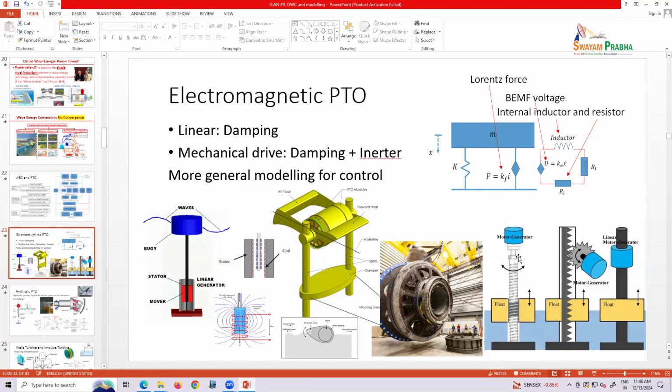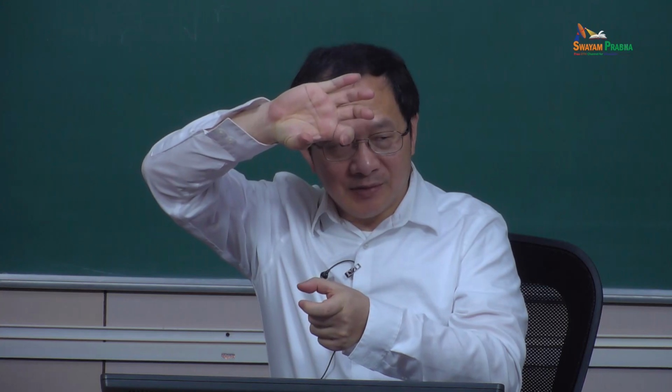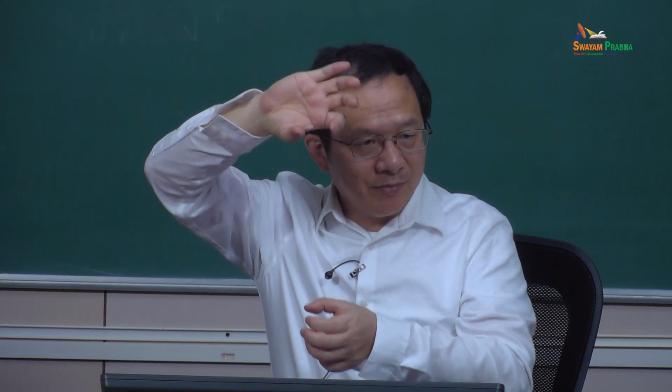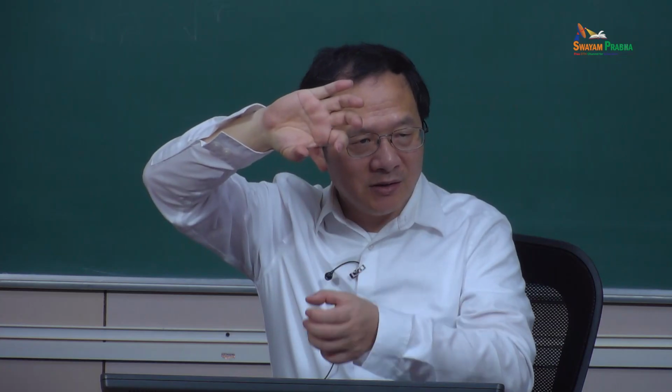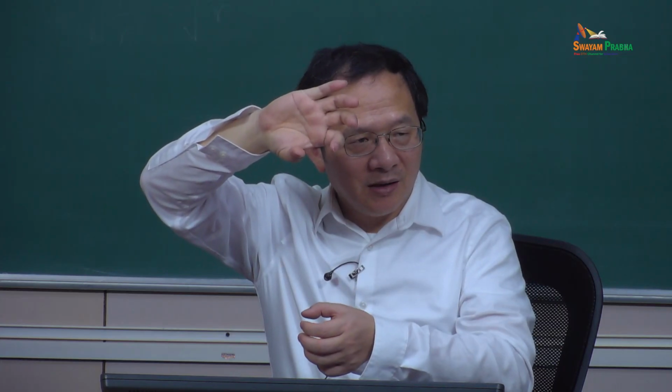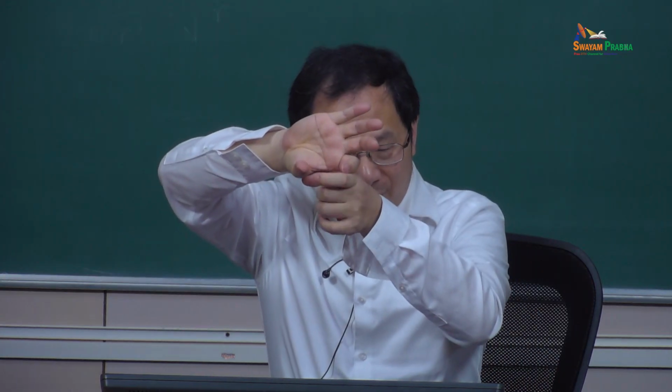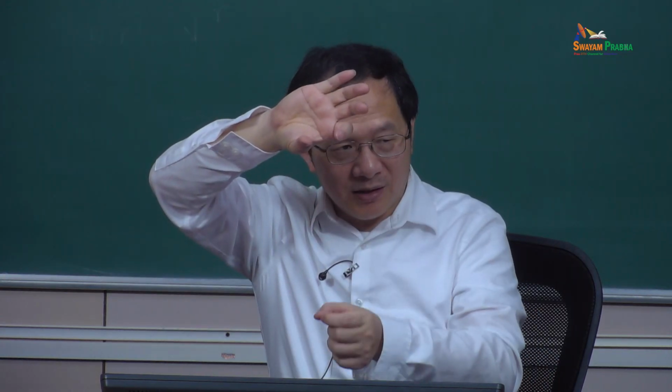For example, the bearing looks like here, and how do you compensate for the thermal expansion, right? For the bearing support, you usually have two ends of bearing, right? If this shaft thermally expands and becomes longer, how do you allow this bearing to move up and down? Therefore, for such bearings usually you have a fixed constraint here, and allow the other end to slide, right?